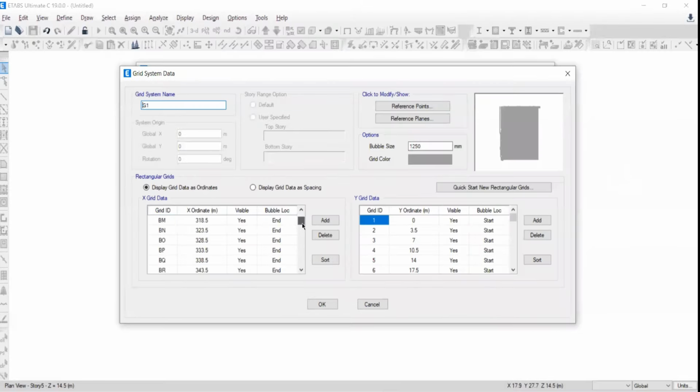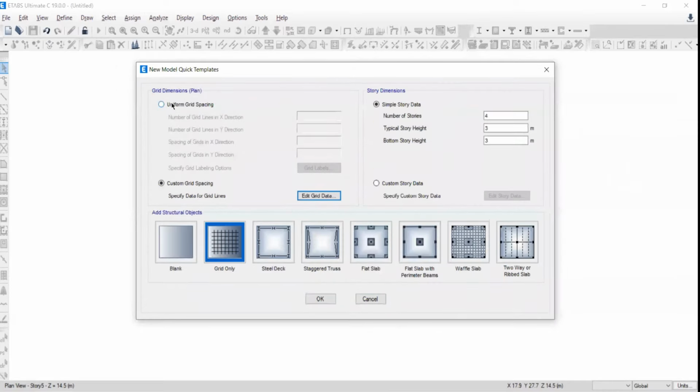Suppose I will find this. Okay, go to this. This is the only change. So I will make it as 4. Now I will come to this, and I'm going to make it as 6. Now come to this, I will make it as 7. Like that, for the selected grid spacing, I'm going to edit here. For the rest of the others, I don't need to change. So that is the advantage of taking the help of the uniform grid spacing option.